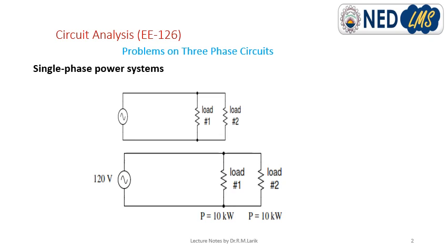So in general, three phase loads are considered either balanced or unbalanced. A three-phase circuit is considered balanced if the voltages, currents, and power factors in all three phases are identical, that is, the same. Conversely, when any of these parameters are not identical, the circuit is classified as unbalanced. That means the impedance is not the same, and the current and the voltage are not the same.